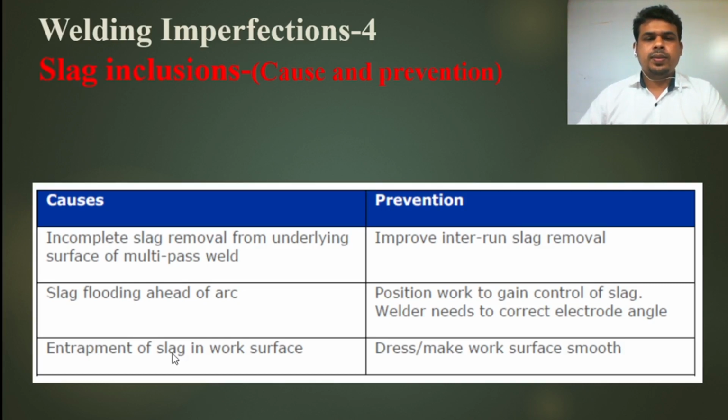Then entrapment of slag in the work surface. So dress the work surface to make it smooth. If there is slag or something on the work surface, we need to clean it, and only then can we go for welding, and we can prevent this type of imperfection.